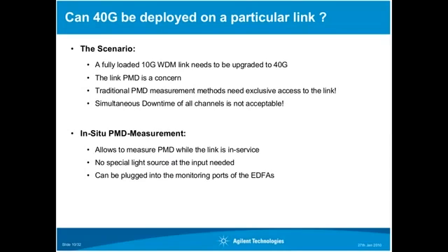As opposed to traditional PMD measurement methods, you want to have a PMD measurement solution which allows you to continue using this link while you're doing the measurement. And this is why we came up with the In-Situ PMD measurement. In-Situ PMD measurement allows you to measure the PMD, and you don't have to turn off the transmission. The idea basically is you ideally just plug the In-Situ test set into some of the monitoring ports of your EDFAs, and then you have access to the whole WDM spectrum, and the analysis is just taking place on that. So that is the basic idea.